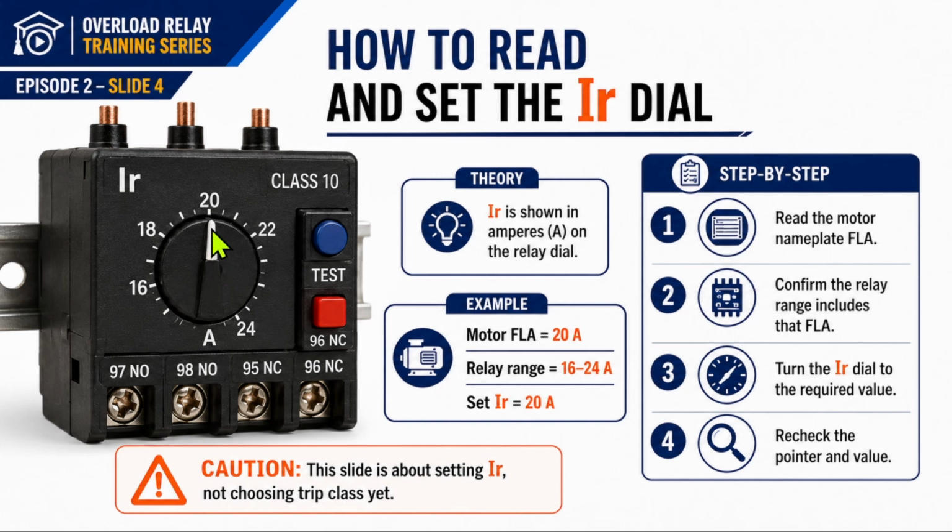So that is a very simple way; we will go further beyond that, bit by bit, deeper and deeper into the setup of the overload relay. You will be a master of it after selecting the overload relay. As I explained in the last episode, read the motor nameplate and confirm the relay range. We have the 20 amp FLA in our example motor, so the relay range we took is 16 to 24 amp. Then we can set the IR reading to 20 amp.